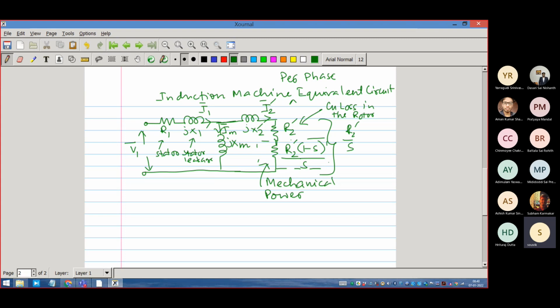It's not at all physical. But due to electromagnetic torque development, the torque will develop because of the interaction of the magnetizing flux and the rotor current. Torque will develop, and then it will go into the speed mode. It will develop the speed and run at a stable speed, the equilibrium speed dictated by the balance equation J d omega by dt is equal to Td minus TL.